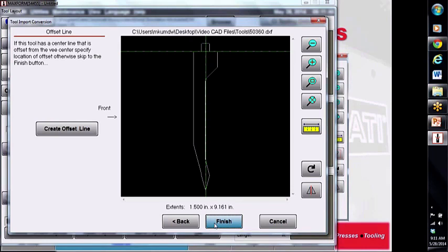With precision tools, you don't have to worry about this, but with older legacy tools, you do. For example, if the tool is made on an older planer, the center line of the punch may be as much as a 64th of an inch off from the center line of your mounting tang. And if you'd like to correct for that, you can. The nice thing about our bend simulation software is that if that correction is made, it stays with the tool file. If this tool is put in forward, that correction offsets the back gauge so that you have an accurate flange with that offset taken into account.